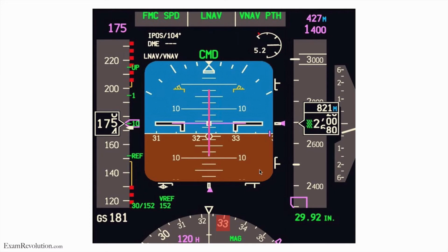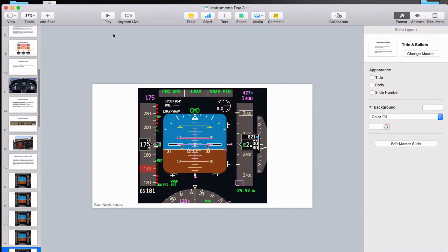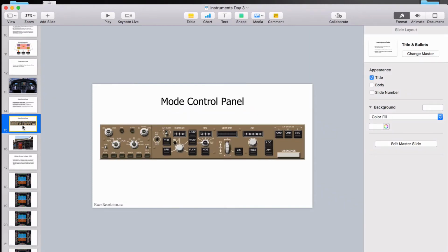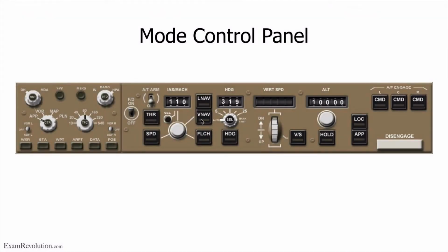So let's say, for instance, as an example, you're flying 175 knots now, right? Let's say you want to fly 140 knots. So we've picked 140 knots. So you would set 140 there at the top, using the speed mode. Let me just go back here to show you this. Actually, it will be much better. So if we go here, there's speed mode, right? Let's say you go speed mode, and then you put there 140. So you use this button and you put 140 there.